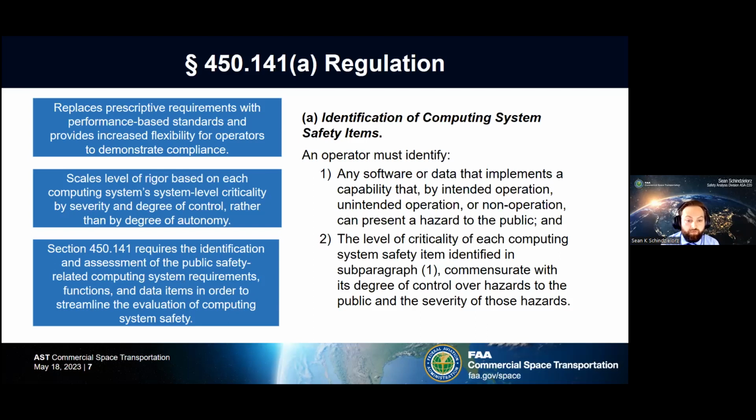To comply with 450.141A2, the applicant must assess the level of criticality of all CSSIs based on their level of control over hazards and the severity of those hazards. Specific assessment methods are not prescribed by the regulation. The applicant is allowed to define a categorization or assessment scheme that best suits their operation. Several accepted methods are provided in AC 450.141.1A.